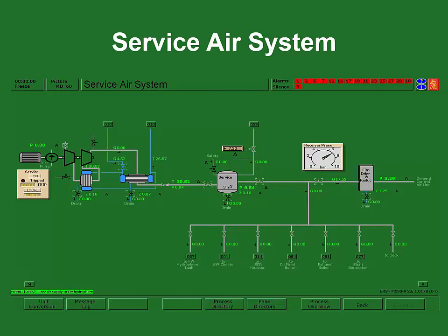Ship service air supplies non-vital systems. Control air supplies critical systems. And today's vessels still use pneumatic controls very heavily, not for the actual controllers themselves, but for control valves. So a loss of control air can mean the blackout of the vessel, that you would lose control of your systems and black the vessel out. So specifically, you have to think about that. And that's why on American ships, we typically have them separate.